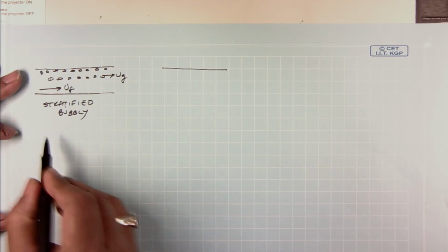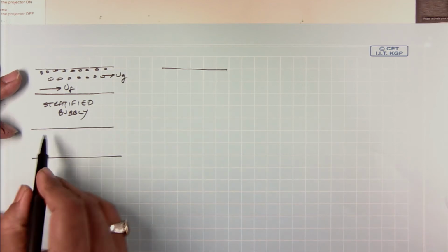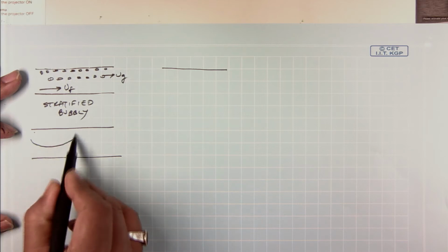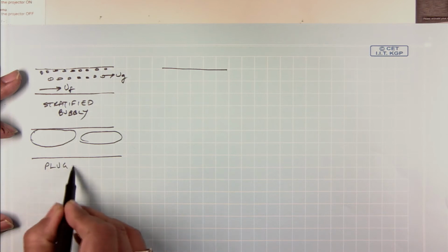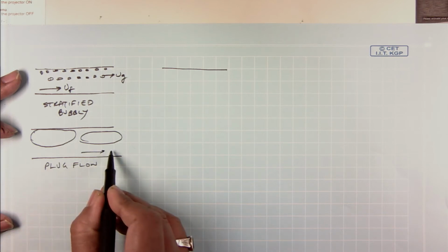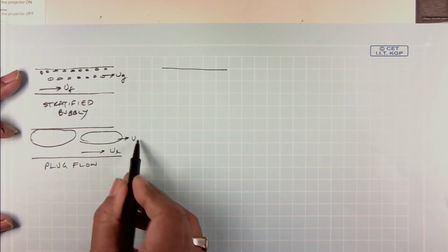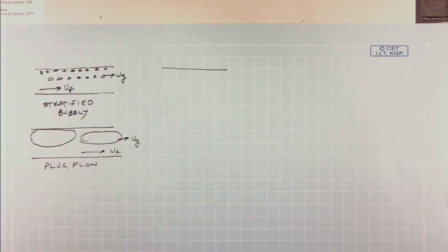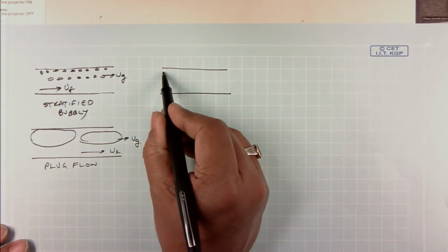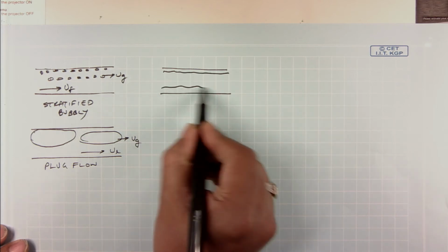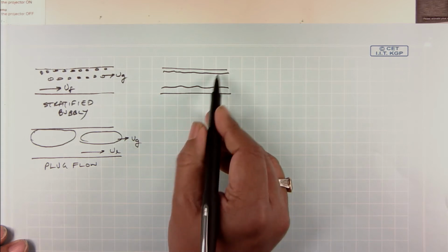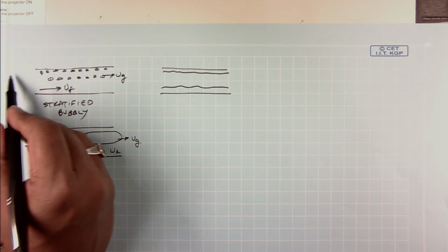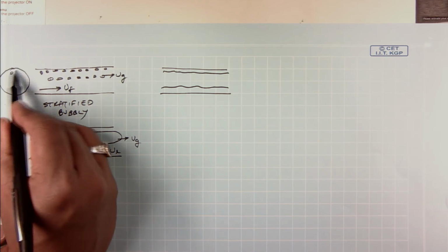So anyway, there is bubbly flow, and then you can also have annular flow, or well, you can have plug flow. But even in the plug flow, your plugs will tend to stick towards the top. And you can immediately see there is an asymmetry in the flow, right? And then you get into annular flow, and even your annular flow will be skewed, because you will have more liquid in the annulus in the bottom and less liquid in the annulus on the top. In other words, if I look at the cross section, I will see more of the bubbles in the top.